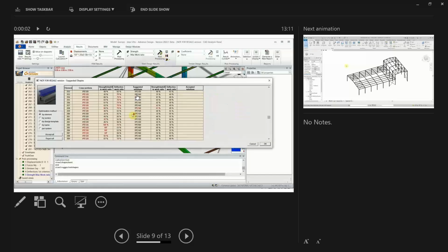Now, over to the optimization. Again, this is very, very fun and easy at the same time. So I personally have great fun with optimization. I set my limit and then I optimize the structure based on that. So if we optimize the structure here, you can see some of them are way overworked. So it's probably something I need to revisit in the model, perhaps check the loading in that area, check the elements if they're modeled correctly, perhaps the meshing.